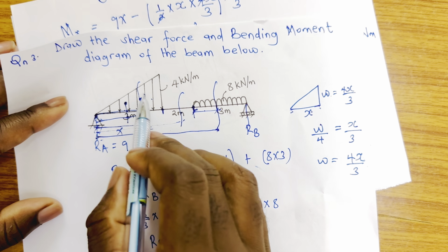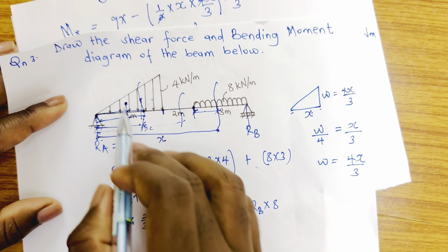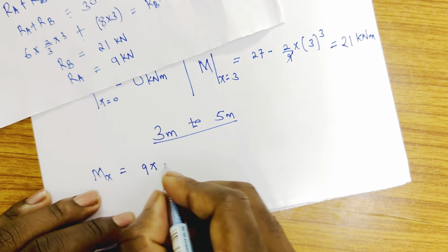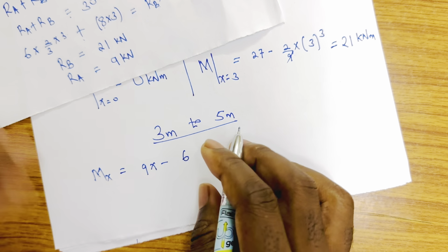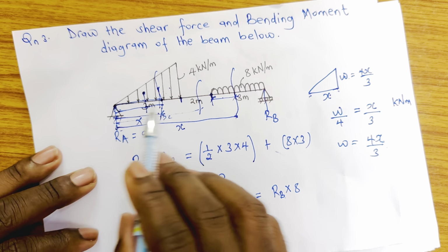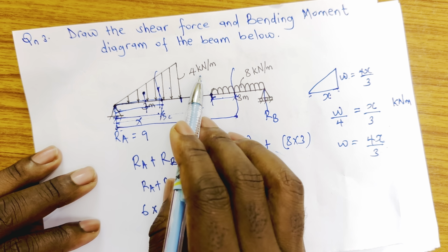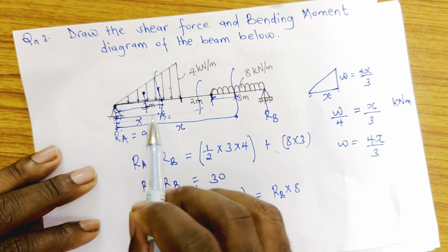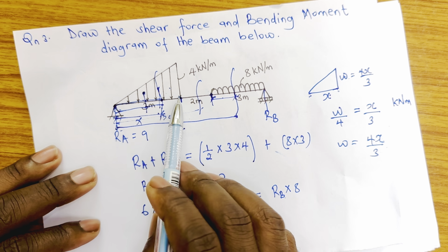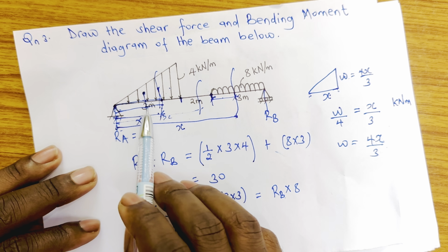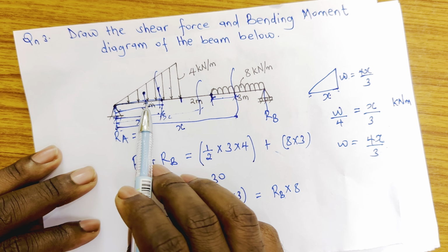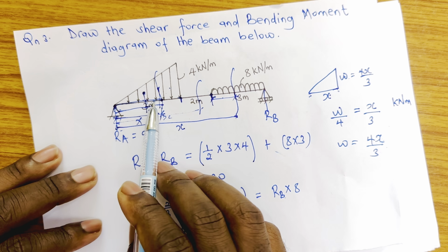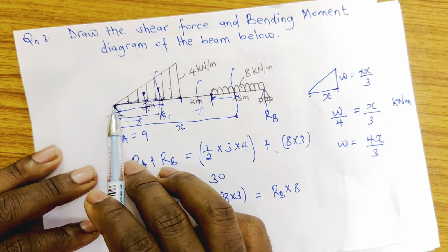Then the second force that is falling there is triangular loading, and if I convert it, the force due to that triangular loading is coming to 6, because area is half times 3 times 4, so this is 6. But where is it acting? It's acting at 1/3 of 3 from here. So 1/3 of 3 is 1. So from here to this part where it is acting, it is only 1 meter. Then from here to NA, it is 2 meter.